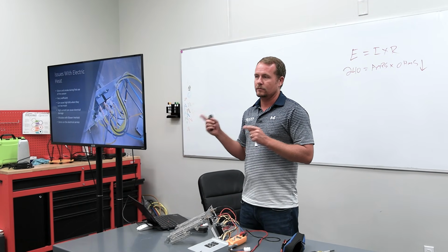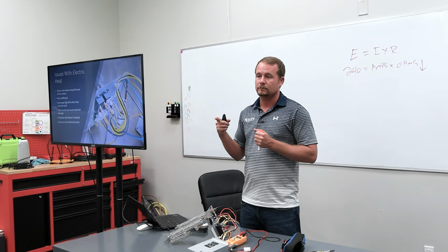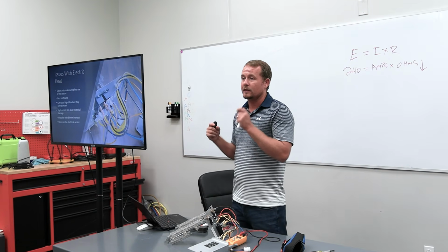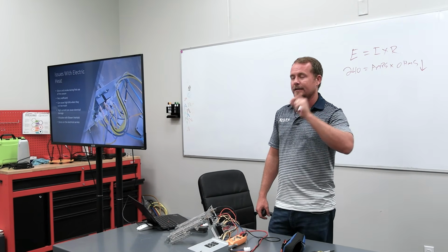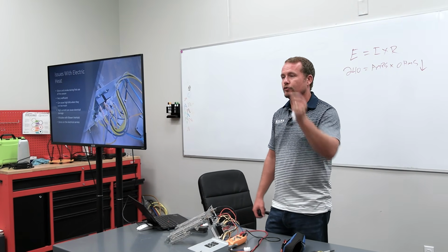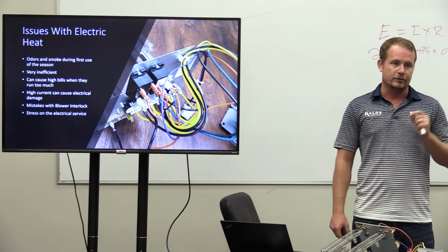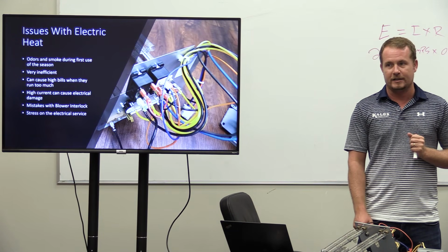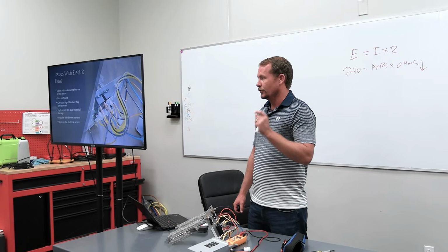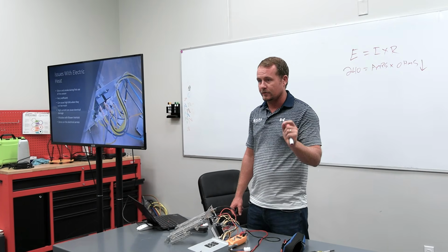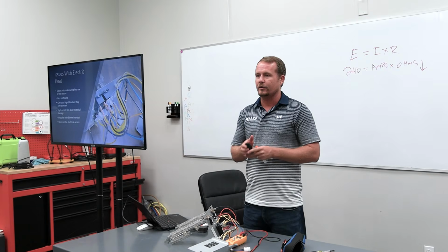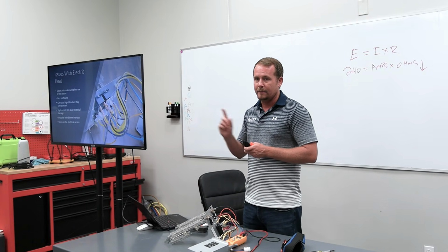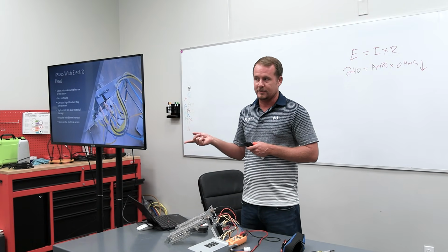Through the thermostat. Yes, doing it through the thermostat service controls, a service menu where you actually go in and you drive on electric heat. So you go into running your second stage heat and then you test it. So you're not jumpering it, you're telling the thermostat to do it. You're still not running it under normal conditions, because normal conditions would be to go to the thermostat, set the temperature way up, and then wait for the thermostat to turn the heat strips on.